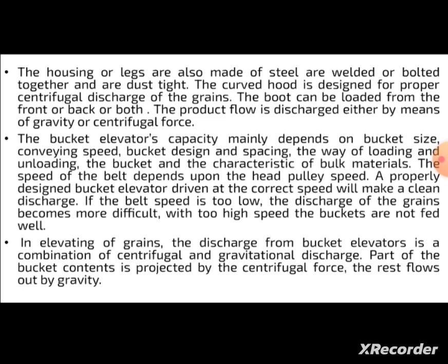So, due to these factors, the conveying efficiency may vary, and the speed of the belt depends upon the head pulley speed. A properly designed bucket elevator driven at the correct speed will make a clean discharge. If the belt speed is too low, the discharge of the grains becomes more difficult, or if the speed is too high, the buckets are not fed well.